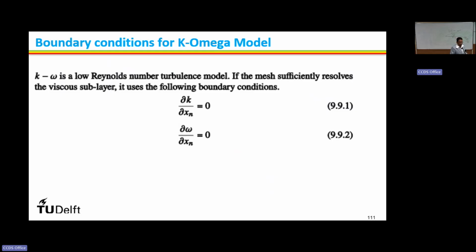You can do a lot of R&D by avoiding the wall function, because the wall function sometimes artificially triggers or induces turbulence. So disabling it sometimes avoids that artificial turbulence, right? In open source codes like OpenFOAM, you can see how these models are implemented, disable the wall function and work on further model development.